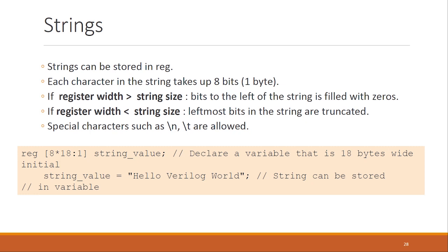But you will see that things like strings, real, integer are not very commonly used constructs in Verilog, because we are dealing mostly with things that can be used to model real hardware. So most commonly we'll be using things like wires and reg variables in Verilog.